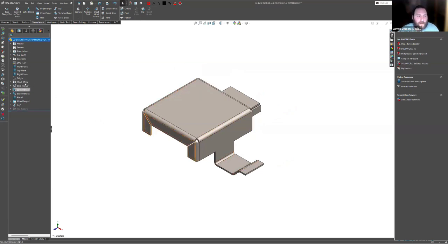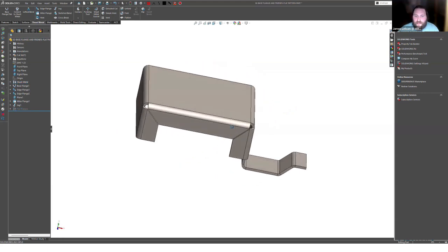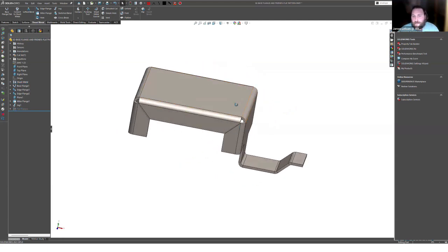And also I want to point out that everything that I've done has been done in what I was calling a sheet metal sandwich. So, I have my sheet metal feature as my top piece of bread and my flat pattern feature as my bottom piece of bread. So let's say we want a circular cutout that sits over this bend.